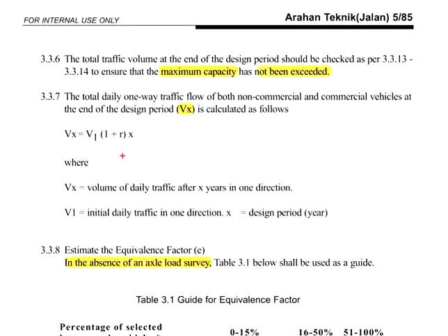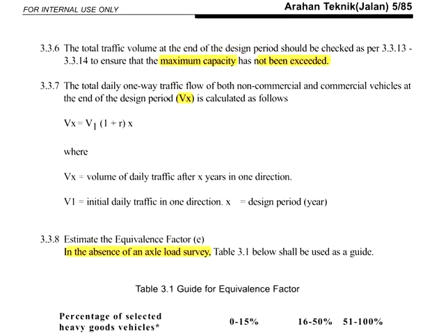You may refer to clause 3.3.7 of Arahan Teknik for the relevant equations. It is stated that the total traffic volume at the end of the design period shall be checked to ensure the maximum capacity of the traffic has not been exceeded. Remember that the design period is 10 years, taking into consideration the construction period.